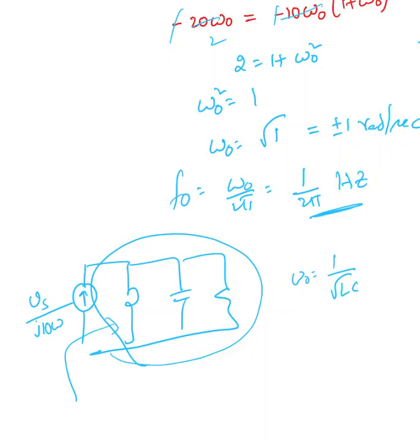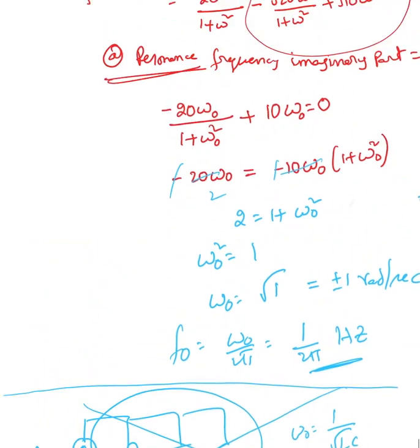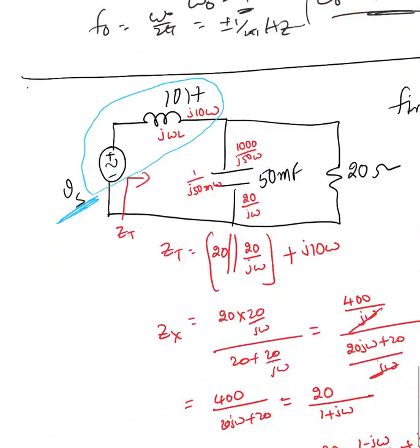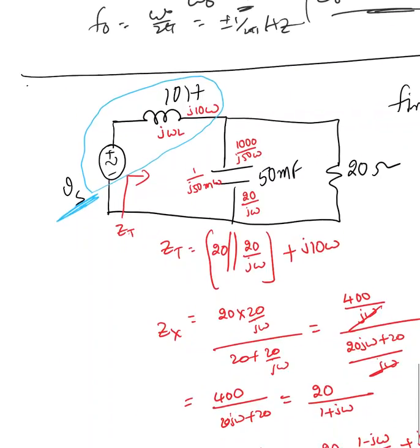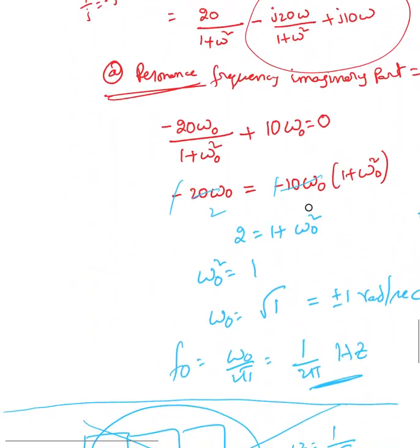Converting a given circuit by using the parallel series combination method or the source transformation method, transforming it into another circuit, will not give you the resonant frequency we are looking for. The resonant frequency varies once you change the circuit, once you convert it into some other circuit. So my strong recommendation is never ever transform the circuit by using the source transformation theorem.